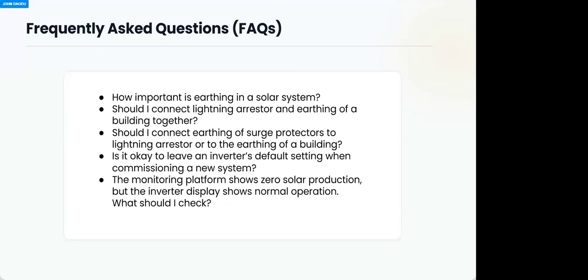So when you connect neutral input and neutral output together, if after you have done your installation, there's a problem on the grid, the pole, and they dropped the wire, and they came back to correct it, by so doing, they interchange the live and neutral, your inverter is not in danger.